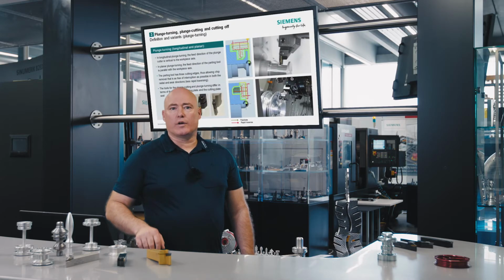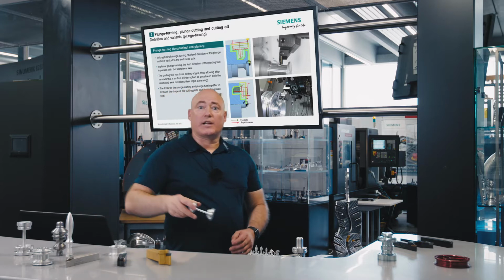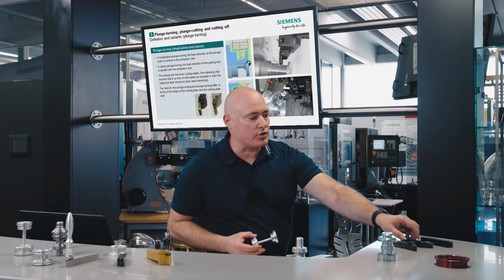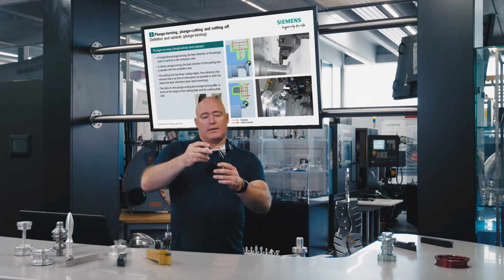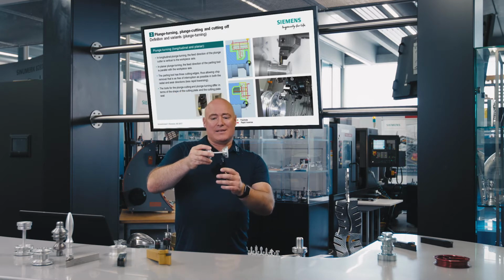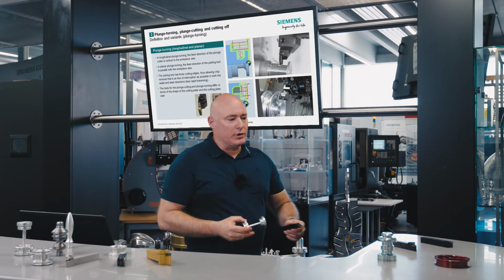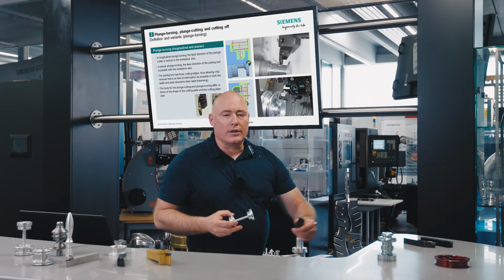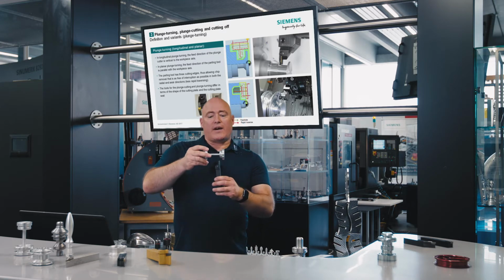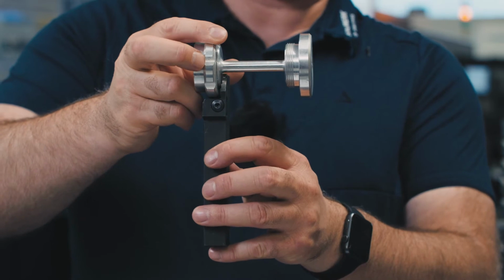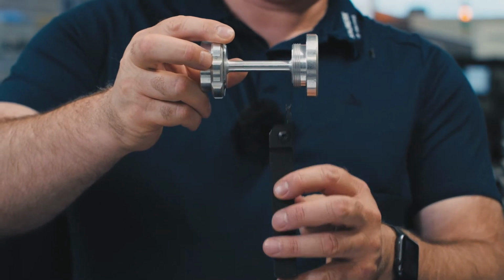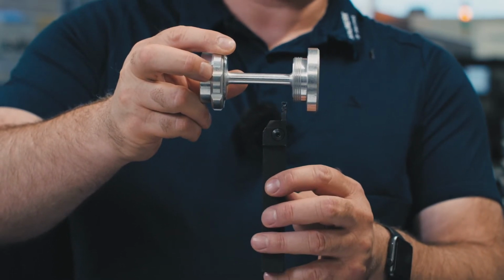In contrast to longitudinal turning, with plunge turning, the stock is removed perpendicularly to the workpiece axis. By contrast, in longitudinal turning, this part can't be finished with this turning tool. You need a grooving tool which is also capable of producing these horizontal walls. The stock is removed by feeding in the vertical direction, immediately followed by a horizontal movement.